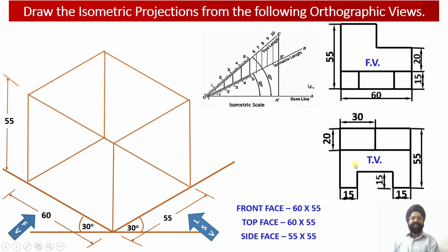So as we have already discussed, we are going to divide this construction into two webs. One web is the horizontal web, which is having this shape. So please check, this is the shape of the horizontal web. So this horizontal web is lying on the base of the solid. And what is the height of this web? The height of this web is equal to 15 millimeter. Now we are going to draw a ring over here, which will be forming the guidance to construct this base web or the horizontal web. So the height of this web has been drawn as 15 millimeter from the bottom of this object.